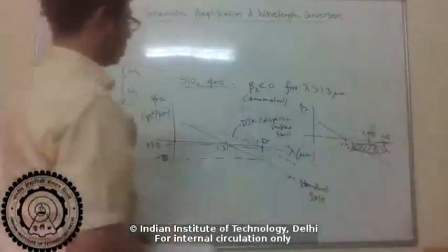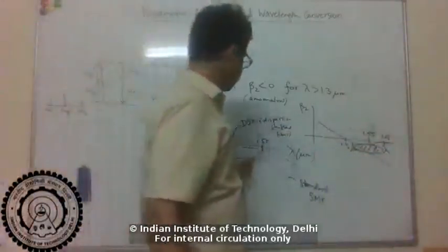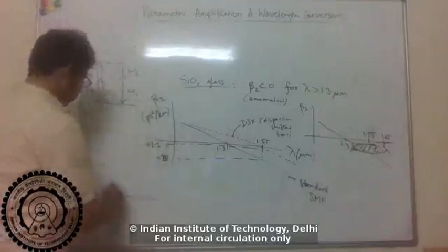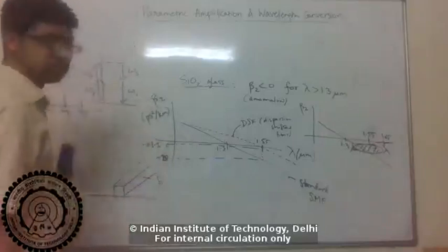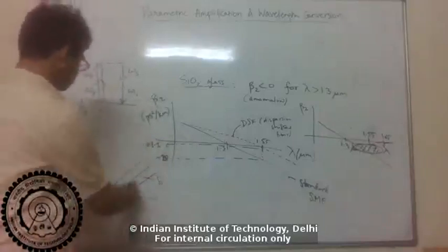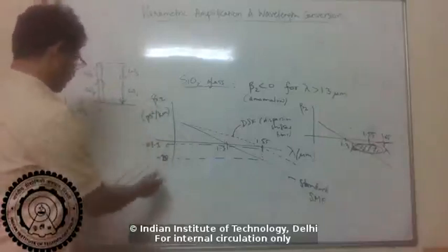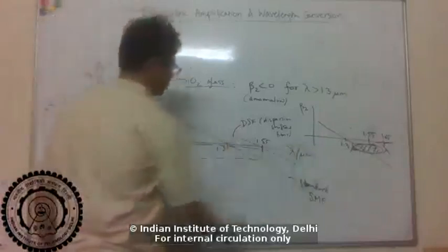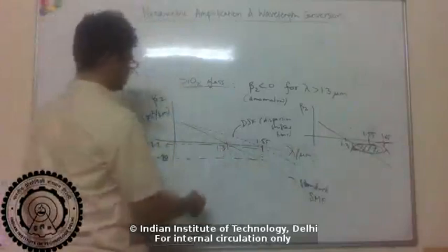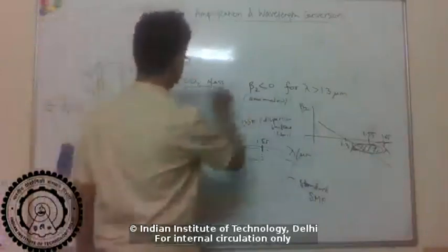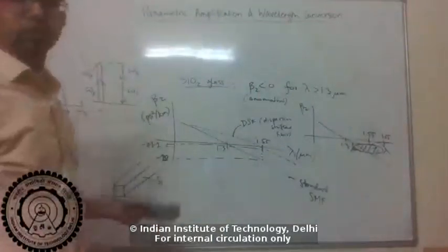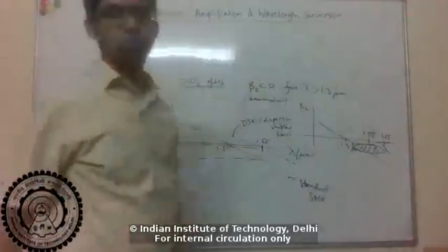Okay, so for glass, it turns out you were just helped by nature. But for other materials, it's not so. For example, nowadays people make on-chip waveguides, right? And typically, if you use silicon, which is one of the most popular materials for on-chip photonics, like electronics also, so silicon in this infrared wavelength range has normal dispersion, which means beta 2 will always be positive here somewhere. Just the material, if you take the material refractive index of silicon, it will always show normal GVD.